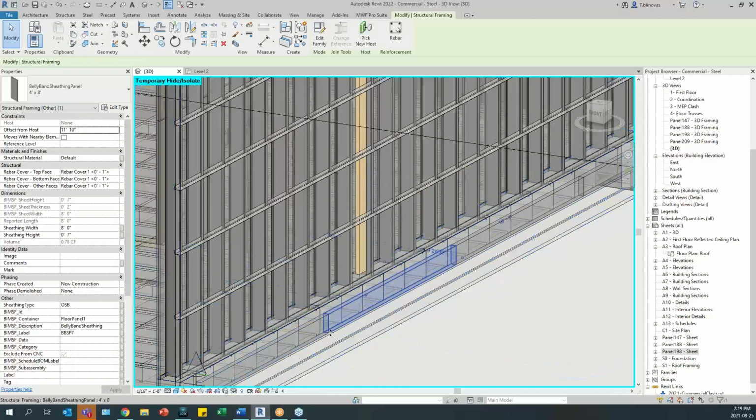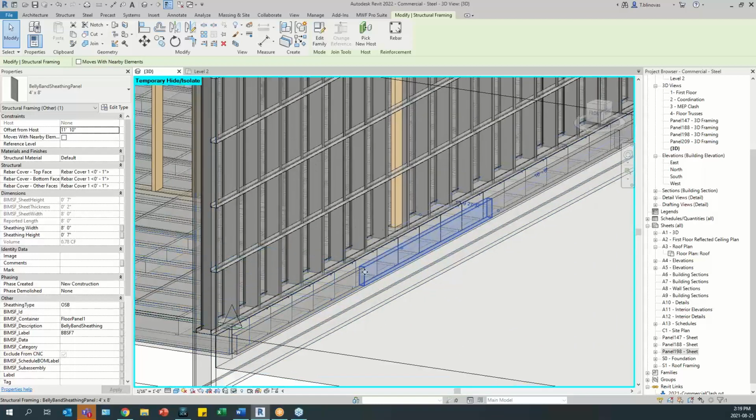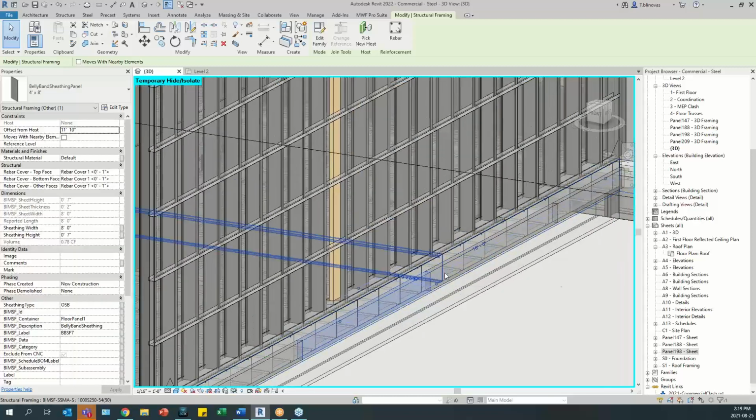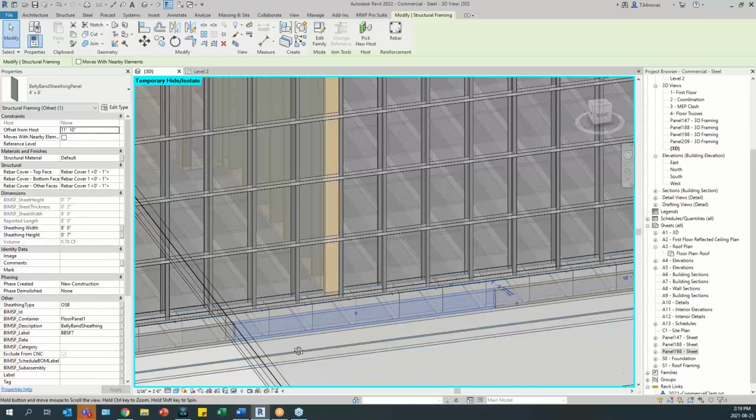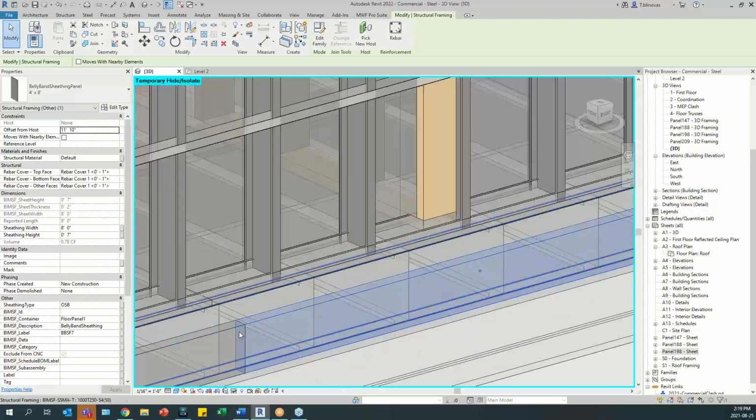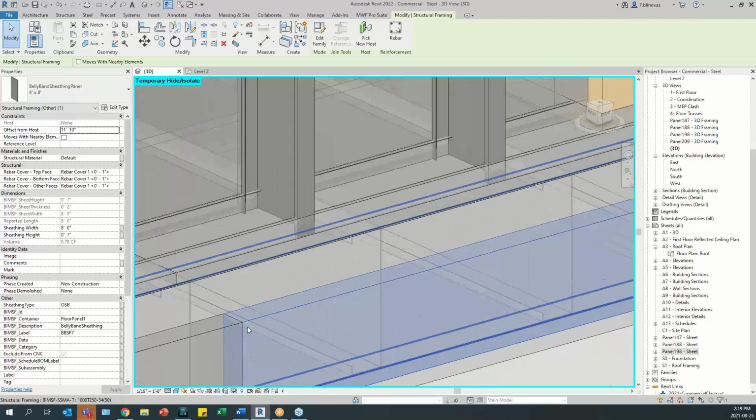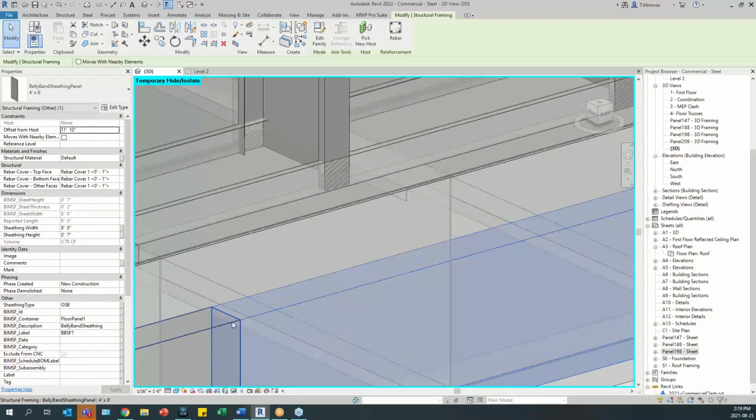And as you can see, it's going to always follow my settings. So the total length here of my board will follow my settings. And the gap option will be showing up in between the boards. Because I didn't add anything, as you can see here, I don't have any offsets, any gaps between the boards.